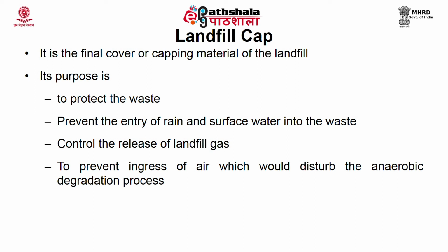Also, it will help in controlling the release of landfill gas, and it will also prevent the ingress, meaning inflow, of air, which would disturb the anaerobic degradation process which occurs within the waste cells.